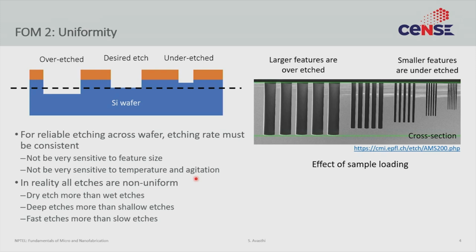If you remember that during CVD we talked about diffusion through a boundary layer of how the precursor needs to get in and the byproducts must get out. Something very similar happens even when you do etching. In this case, the etchant must get in and the byproducts must get out. And if it's just a static solution, then you are just depending on diffusion to do this process, but that can sometimes be non-ideal.